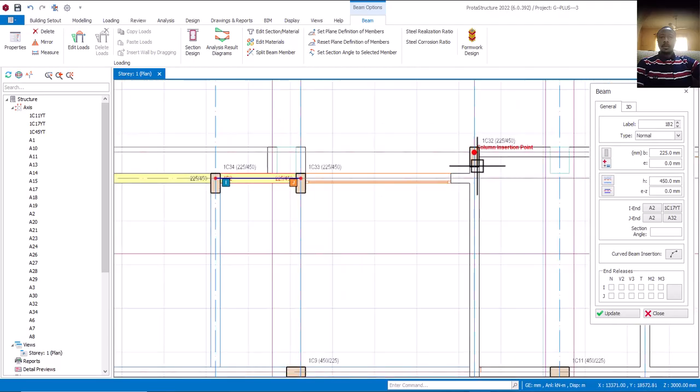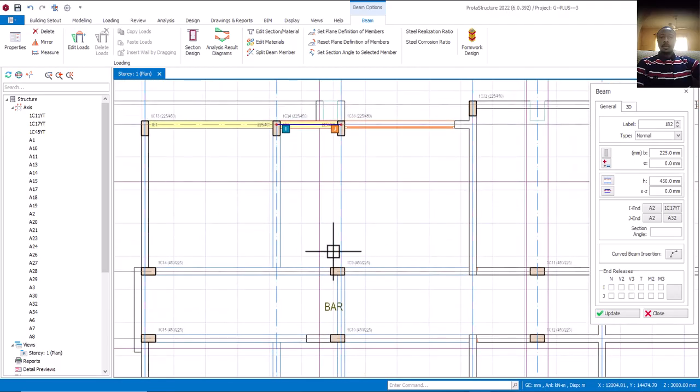Because there's a beam here, this is the primary beam, so which means I have to do this one first. I'm looking at this span here. I have to use a bigger depth. Is that okay? 600. Let me use 600 from here, to this point here.